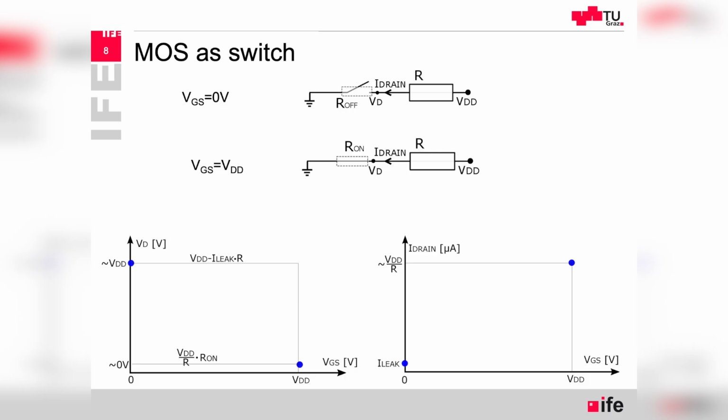On the other hand, when we want to switch on the switch, VDD is applied to the gate. That means a voltage that cannot exceed a certain value so as not to damage the transistor, but typically it could be, for certain technologies, 5 volts or 3 volts or 1.8 volts or lower, depending on the technology node and the oxide thickness.